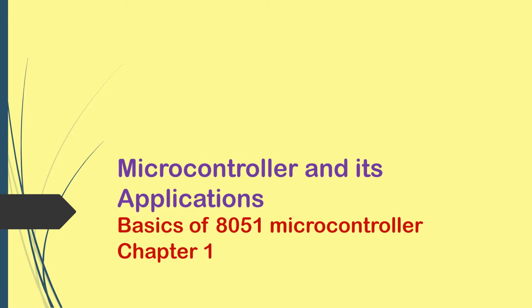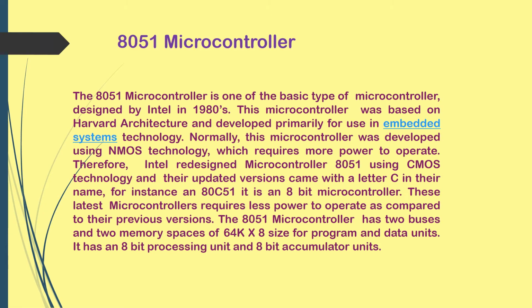In general, microcontrollers are classified as 8-bit microcontrollers, 16-bit microcontrollers or 32-bit microcontrollers. As far as memory is considered, they are classified on the basis of external memory microcontroller and embedded memory microcontroller. As far as instruction set is considered, microcontrollers are further divided into two categories: one is CISC and another one is RISC. So in general, microcontrollers are the building blocks of embedded systems.